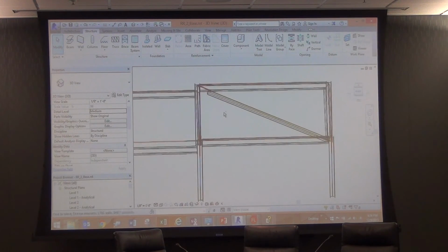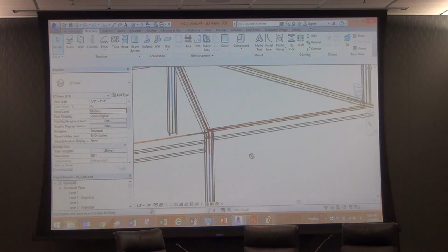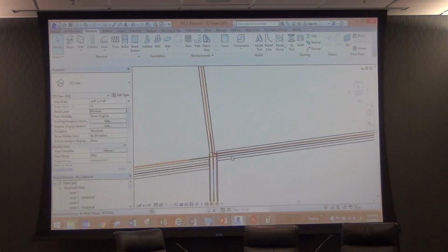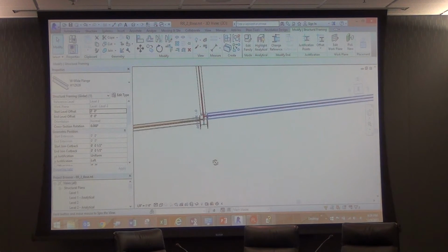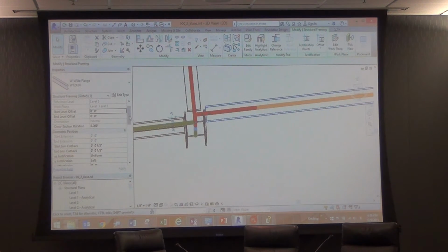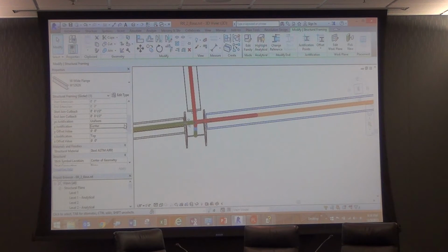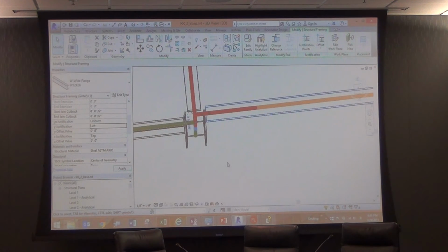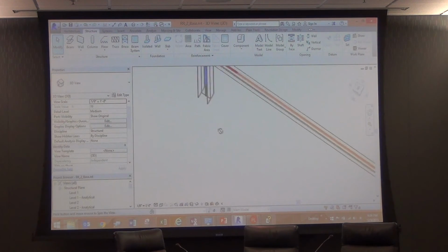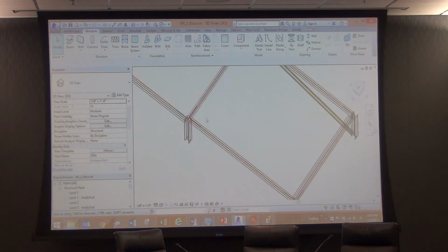And then the other one that I was going to show here is, on this one, the member in this case, I did an offset on it where I did a Y justification left. And that's not necessarily what you would probably do. Actually, I want it to be center. So now it's back on the column. So you can see that moves with it. If you did a left justification, then it moves that analytical line with it. So you need to kind of pay attention to that.